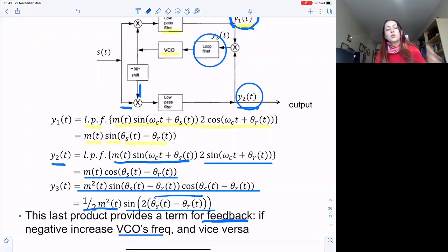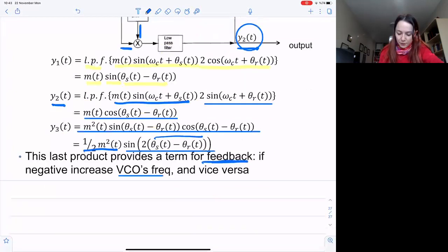So this is a sort of complicated looking design. It's known as the Costas loop. It's like a PLL, and it's used to demodulate double sideband suppressed carrier. Earlier in our demodulator structures that we studied for double sideband suppressed carrier, we mentioned the squaring loop, which is a little bit simpler, easier to understand than this Costas loop. And we also, of course, said, whenever you have the carrier available somehow in the receiver, you can easily demodulate double sideband suppressed carrier.